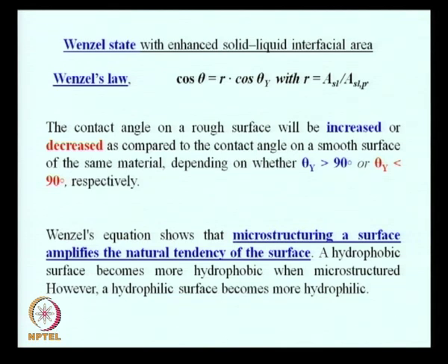So, this would tell us that microstructuring a surface amplifies the natural behavior of the surface. So, if you have a hydrophobic surface and you provide such structures, then the surface will become more hydrophobic. If it is hydrophilic to begin with, then providing these structures will increase the hydrophilicity of the surface.